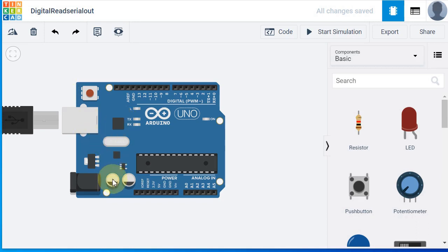All digital signals applied to a microcontroller carry logical status information about whether it is on or off. In other words, whether it is high or low, and the voltage level will indicate whether the status is high or low. The voltage for high may be 3.3 or sometimes 5, and for low it is 0.